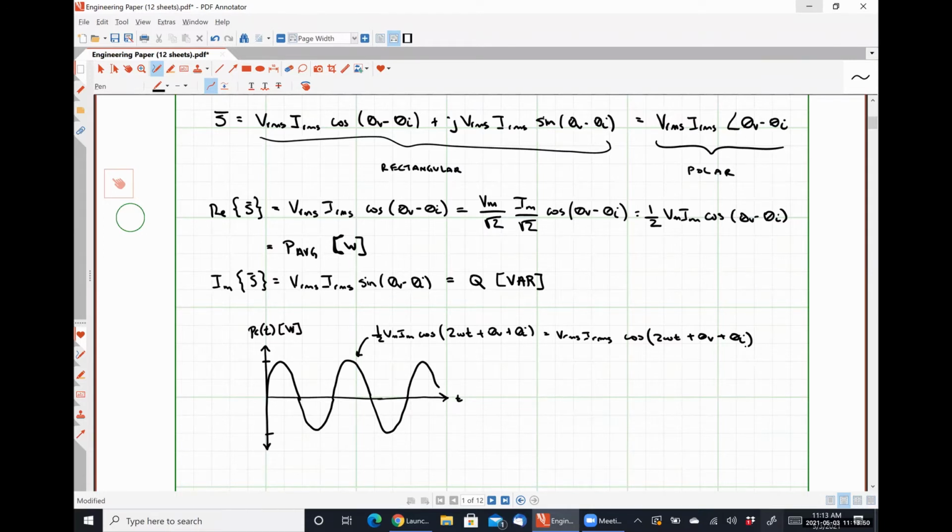Everywhere above that horizontal time axis shows where that capacitive or inductive load is absorbing power, and everywhere below that horizontal axis is where that load is supplying power. So for a fully inductive or fully capacitive load, we are absorbing power for a half cycle and then sending it back to the generator the next half cycle, over and over again. So this part of the power is completely incapable of doing any work whatsoever, because it's just received and sent, received and sent, over and over again.